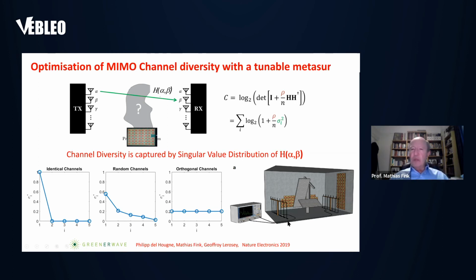I am in a room, I have, for example, 4 or 8 antennas that transmit, like a MIMO configuration, and 4 or 8 antennas that receive. And initially, my room has this boundary. It's not a perfectly random room, but I put some surface on it. And I decide to change my configuration to maximize the value of my singular values.